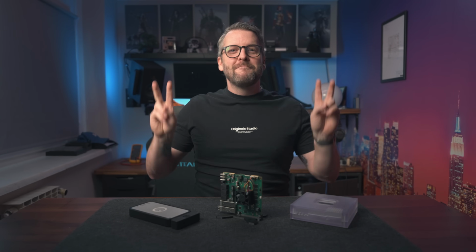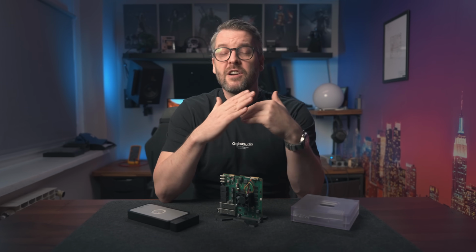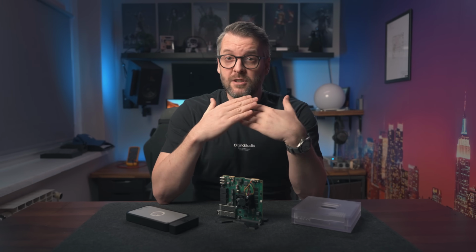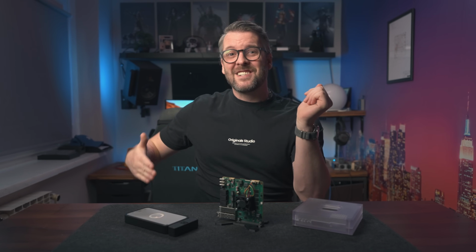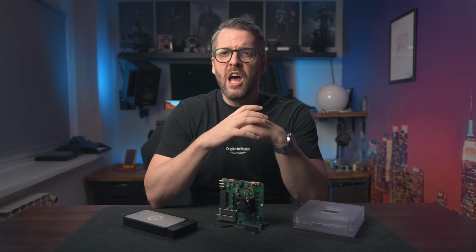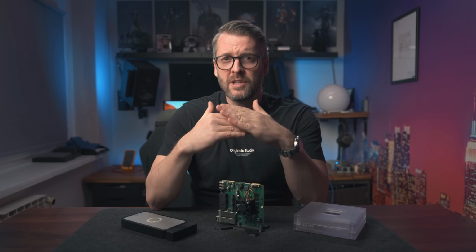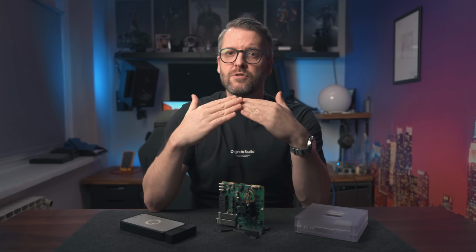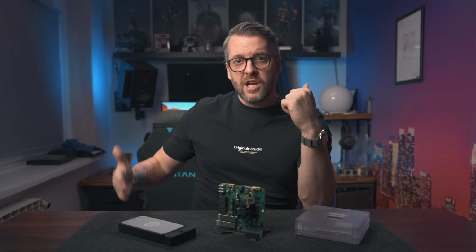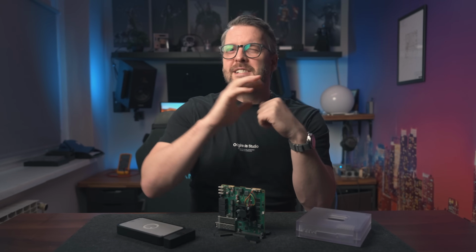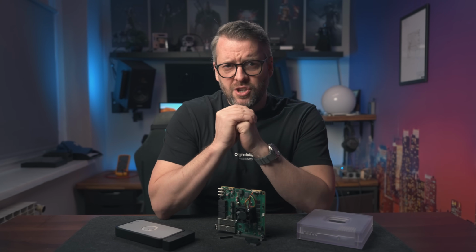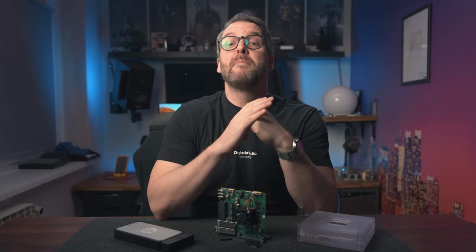And here's where the somewhat working memory I mentioned earlier comes into play. For us to be able to run what is called a DDR centering, more on that soon, we needed to build a BL2 that was good enough for the memory controller to not report any major issues when booting up. Except it did report a major issue, but to our surprise, booted up anyway.